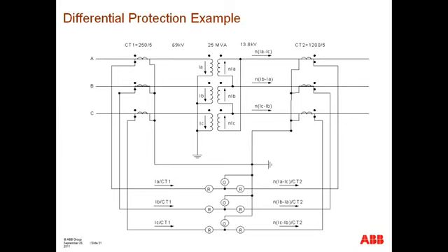So that is a percentage of MVA. Depending on what the loading of your transformer is, that may become greater as a percentage of the current that's flowing on the low voltage winding, or smaller, at which point the relationship between one winding and another is going to be skewed more or less significantly. So I hope that addresses that question.